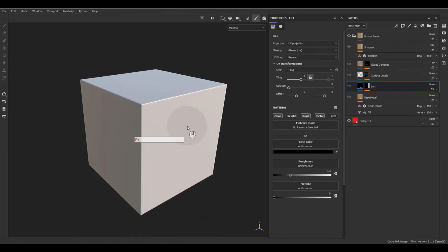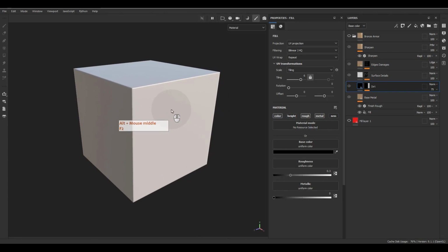So we can solve this kind of problem with these two different techniques. The first solution was using a single smoothing group for the whole model. After that, when you bake, there are no lines, there are no mistakes on the normal and your mesh maps.